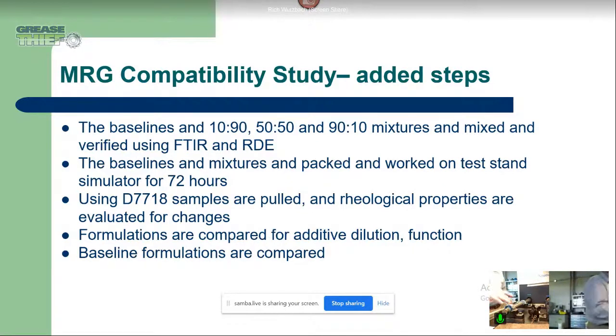When we're done, this is when we would take our samples. We would use the grease thief, which I've demonstrated multiple times here. We could use the pillow block sampling kit and take the grease, and we're really going to be reaching down inside to the bearing here to get that grease that's been in there and working that whole time. Use that grease for our analysis.